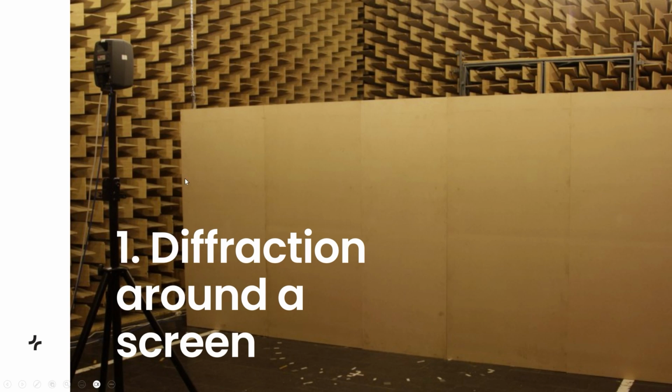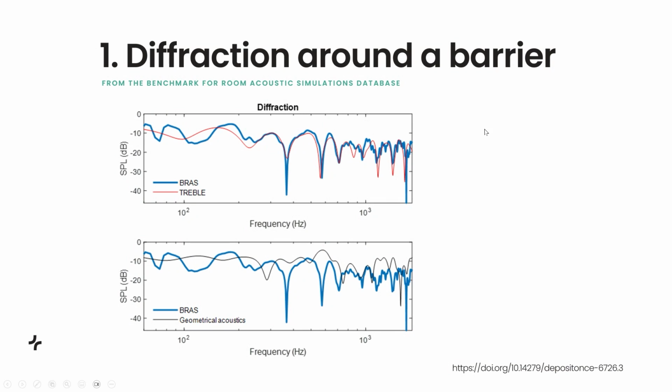So this is a measurement scenario from a database called the Benchmark for Room Acoustic Simulations, which we have been very fortunate to get to work with to benchmark our simulation algorithms. And here we have a sound source that emits some sound that kind of bends around this obstacle, and then we have a receiver or microphone on the other end. And what we see here is that if we run a wave-based simulation for this kind of scenario, for especially the sort of low to mid frequencies where you have a lot of diffraction, sound bending around this obstacle, then we can model this quite precisely using Treble, using a wave-based simulation.